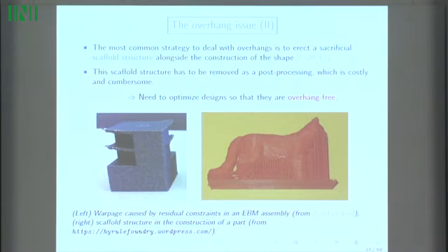So this is nice. For producing some parts, there is no way out of erecting a scaffold structure. But in general, scaffolds are cumbersome because they use more material. They take more time to build, the scaffold and the shape together, and the scaffolds have to be removed in the end, which is often time-consuming, and sometimes this has to be done by hand, or if there are some internal cavities, it's difficult to remove the support.